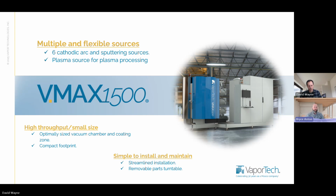One of the things that's really important on the functional side, well, actually important for any kind of coating deposition, is the pretreatment, making sure that the coating is being applied on a nice, clean, fresh surface that's well prepared. We do that with temperature, and we also do that with etching, plasma treatments prior to depositing the coatings. Really, really important for building those really tough, durable coatings.